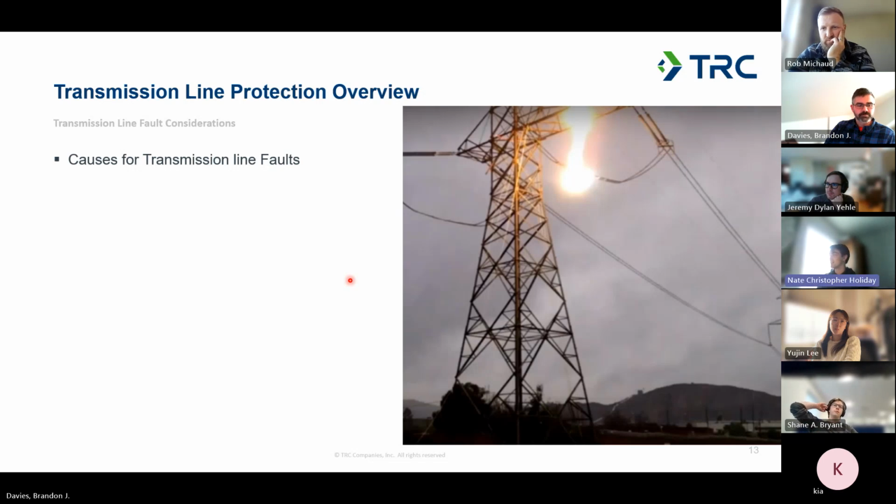Yeah, you need like squirrels in the line, right? Can't that cause a fault? Yeah, animal contact would be a good one. For a large transmission line, with the spacing we're talking about in the transmission system, it would have to be a very large squirrel. So that's a bigger issue on distribution systems, but definitely animal contact would be a cause. Any others?